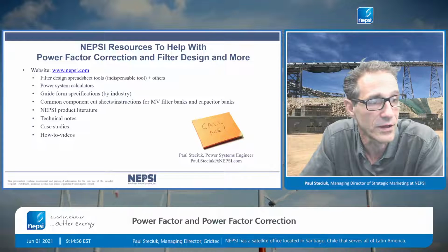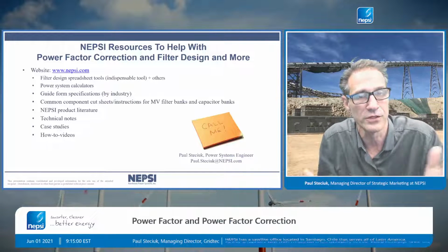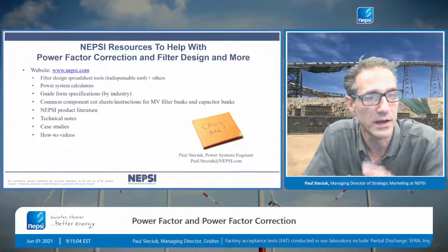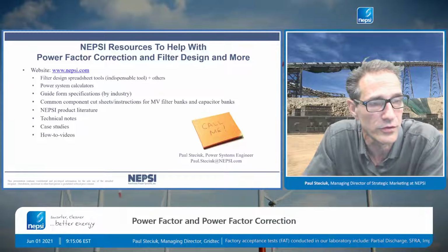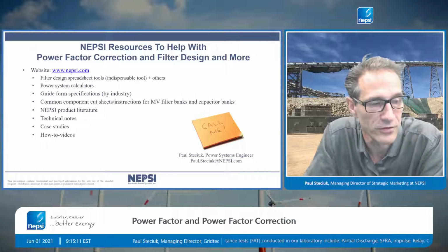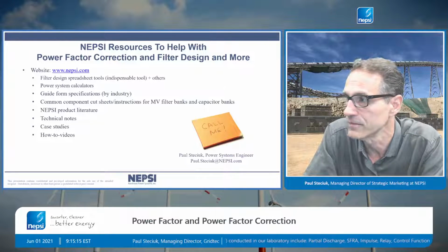We oftentimes see it being applied in chip manufacturing plants to support voltage during power system faults outside of the network, because capacitor banks will prop up the voltage during a fault because it supplies reactive power. And a StatCom can do the same thing.